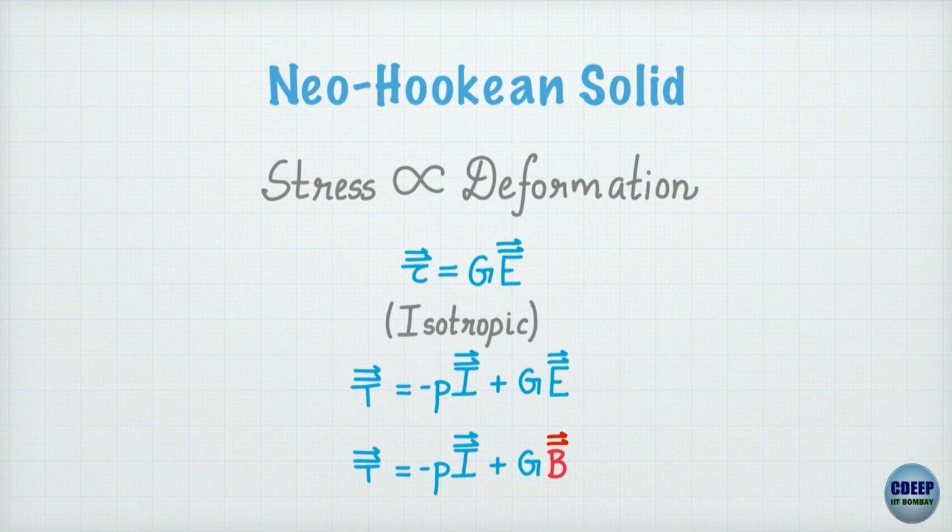When making this statement, we made lots of assumptions. One of them is that the material is isotropic, right. So, G is not a function of direction. There are many other assumptions that have gone in, that the stress tensor is symmetric, right. We have also included the fact that the system is frame indifferent because rotation has been taken out, right.